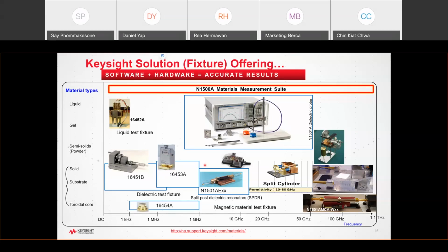In that case, because the waveguide has dispersion, your S-parameters will not be accurate, so it will give you a wrong answer. If you can live with some gross error in the measurement, then that will work, but I cannot quantify the error because the waveguide is dispersive. That's why we want the sample to fit inside the waveguide, so there is no waveguide dispersion.